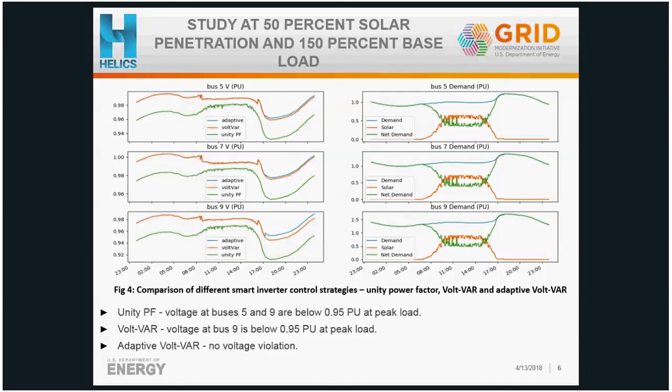Now, the directional information for this sensitivity is in the same direction, whether you calculate for a particular condition or you pre-calculate. The reason for that is we do know that the QV sensitivity is such that if we inject Q, the voltage has to improve, and if it's otherwise, we are in a voltage collapse situation, right? So the directional information is correct, but the exact sensitivity is inaccurate, or in other words, we don't have exact information. But for this test case, that worked out fine. Moving forward, we would like to change that to computing at each given dispatch.